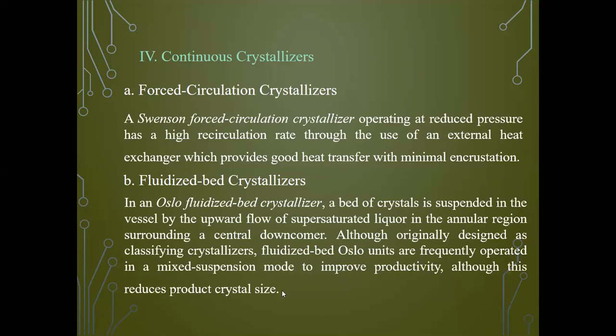So there is some sort of an opening in the crystallizer unit, and your supersaturated liquor remains suspended in the annular region surrounding this central downcomer. Your unit is in a mixed suspension type of mode, meaning a certain amount of the grown crystals remain suspended in the solution while a new batch is being processed. That is why it's called mixed suspension mode.